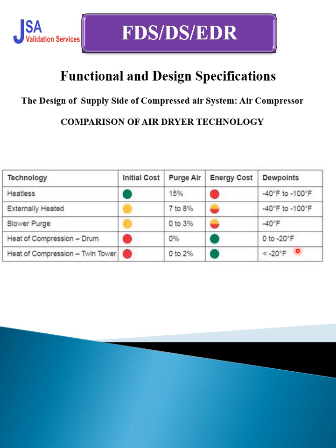If we require compressed air with a dew point of -40 Fahrenheit or -100 Fahrenheit, then it cannot be used in that case. So you should clearly mention in your user requirement specification which type of air you require, what is the class of air.